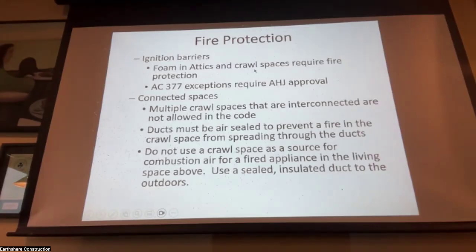AC 377 is an exception to the code if the foam is tested by NFPA, the National Fire Protection Association, and meets certain criteria. But AC 377 is not part of the code. It requires authority having jurisdiction approval, so you have to have your code official approve that.